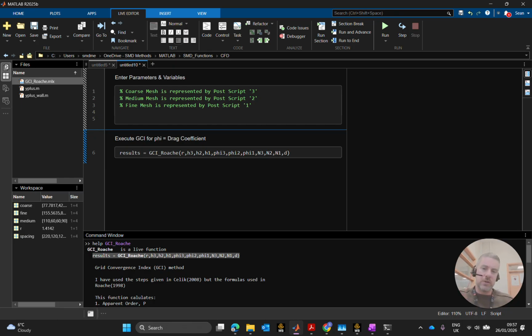But it isn't averaged, right? It's not time averaged. It's spatially averaged only. There's no time dimension in it. Right? It's spatially averaged at this flash in time. That's what I meant when I said snapshot. Not that it just picks a value and says, yeah, you look good here. It means at this snapshot in time, time doesn't change. This is the average spatial results.